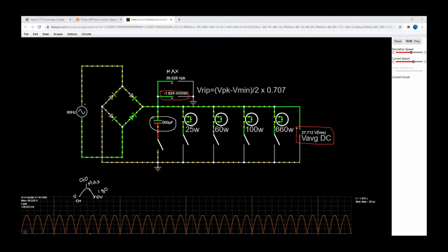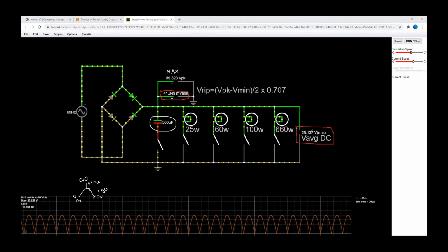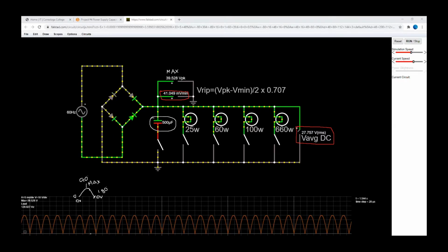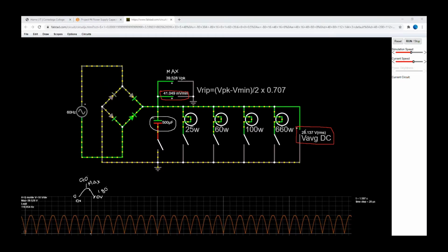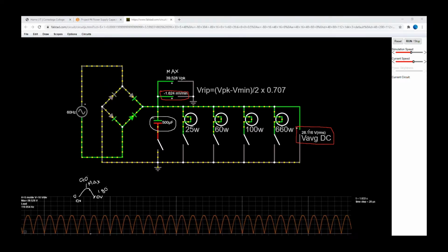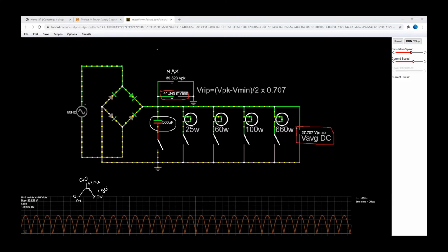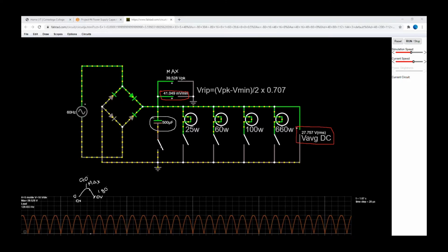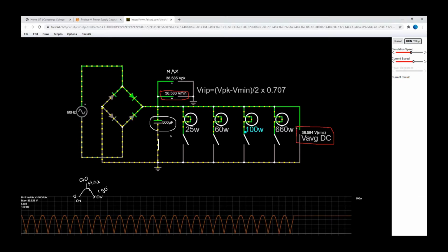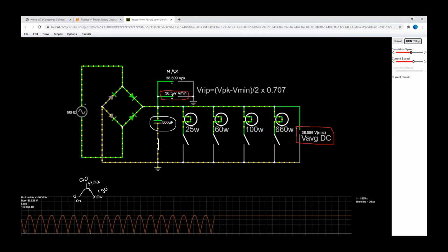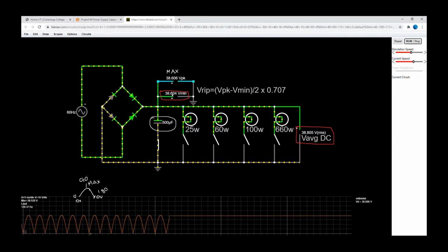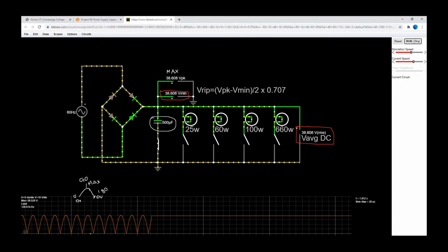At this point in time, that average voltage is being measured at roughly 28 volts. There's a little fluctuation because of the simulation, but the average voltage is 28 volts. So now let's close that switch and see what happens. Do you notice what happened as soon as we close the switch? You can see that the max and the minimum are equal because we don't have a minimum anymore, okay? So I'm going to stop the simulation.